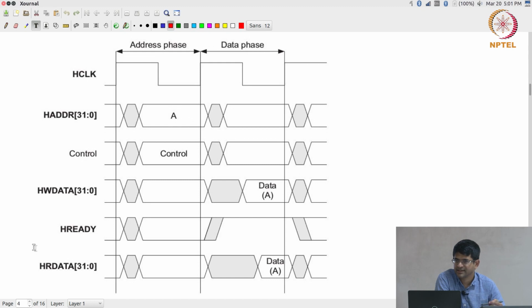The interesting thing over here is that effectively we are splitting the writing part of the bus and the reading part of the bus into two separate components. In principle, at least according to this diagram, I can both write and read at the same time, because I have two sets of wires, one doing writing, the other doing reading. Usually that is not very useful because I only have one address. So all that it means is I can write something into the same address that I am reading from. That is not a very common occurrence, but this is used only for illustration, to tell you that in principle it is possible to have writing and reading happening at the same time.